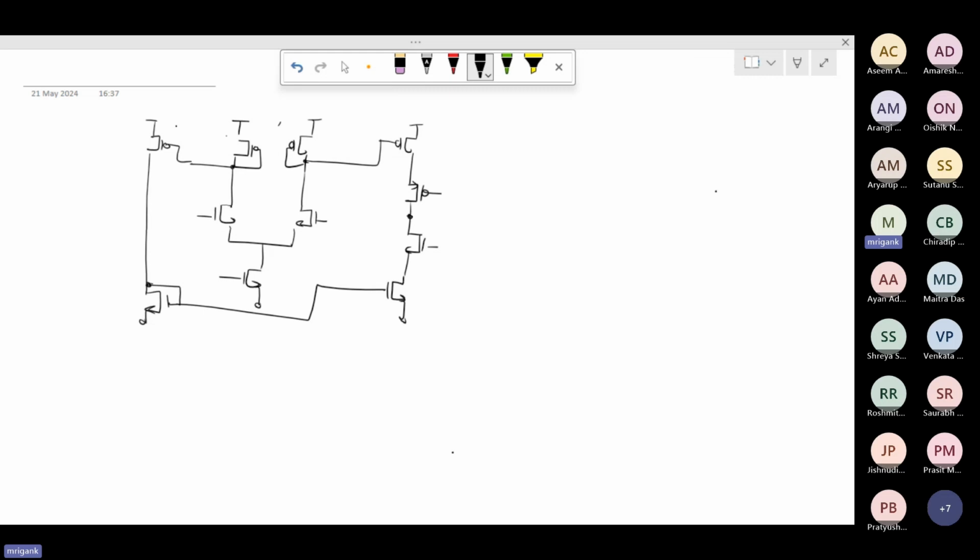So what we saw was we are putting some output cap over here. This is the final output, V out, and this is your V plus in, V minus in, and you have some VB over here. And we saw that we have to provide some significant delta V. If this is 500 millivolt, you are providing something like 476, right? So the difference is this much.